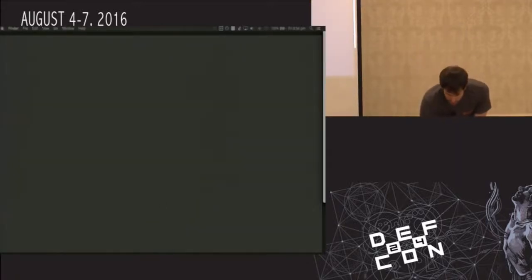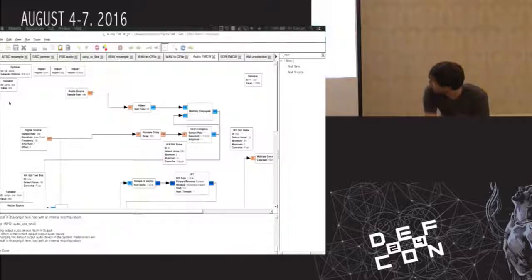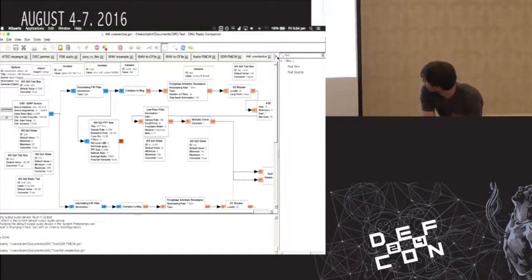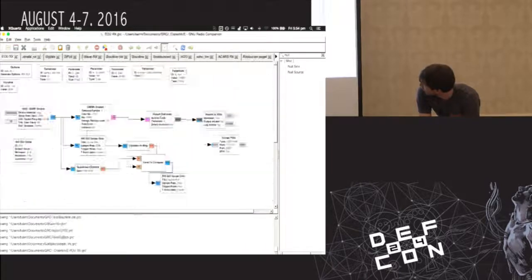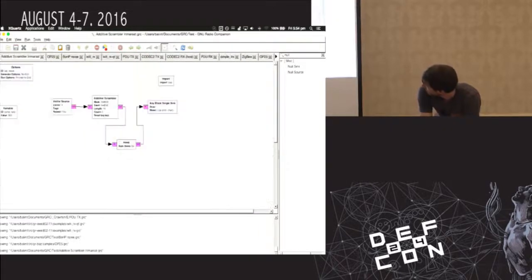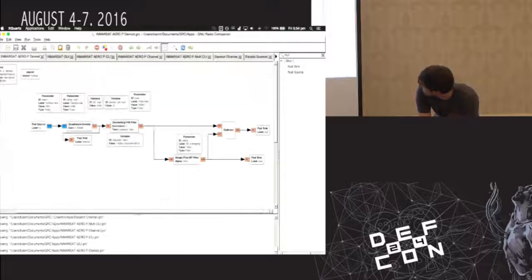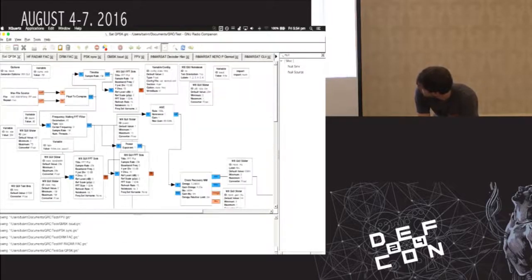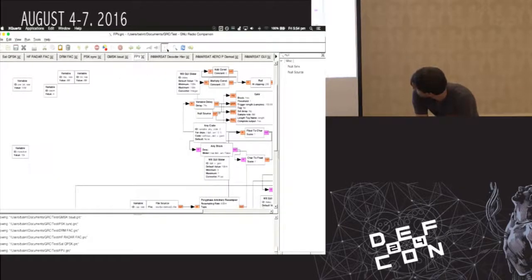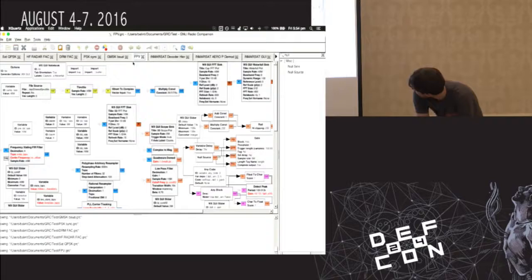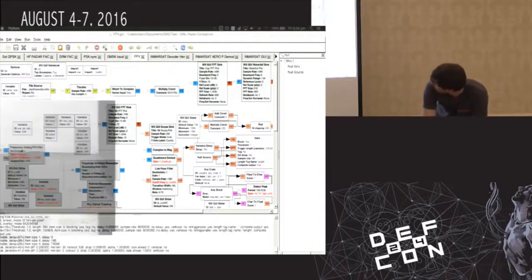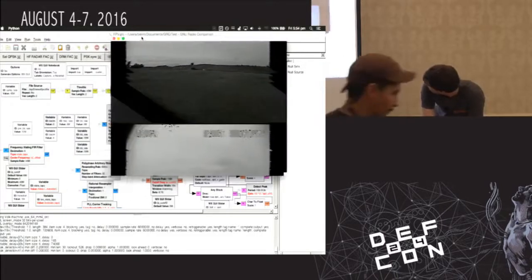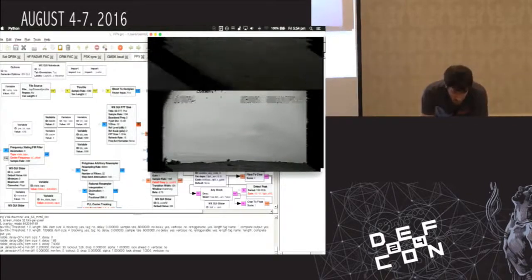And in the last minute, I didn't get time to show you, but you can also do analog video decoding. FPV on drones ends up using NTSC over FM. That's the one that I've seen anyway. And so you can create a flow graph. I was mucking around with this a little bit. Still very experimental. Let's see. So my vertical sync needs some improvement there.